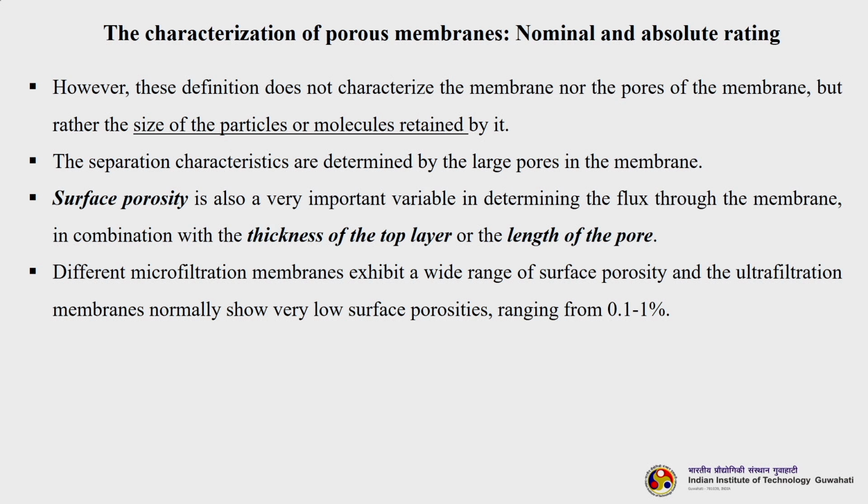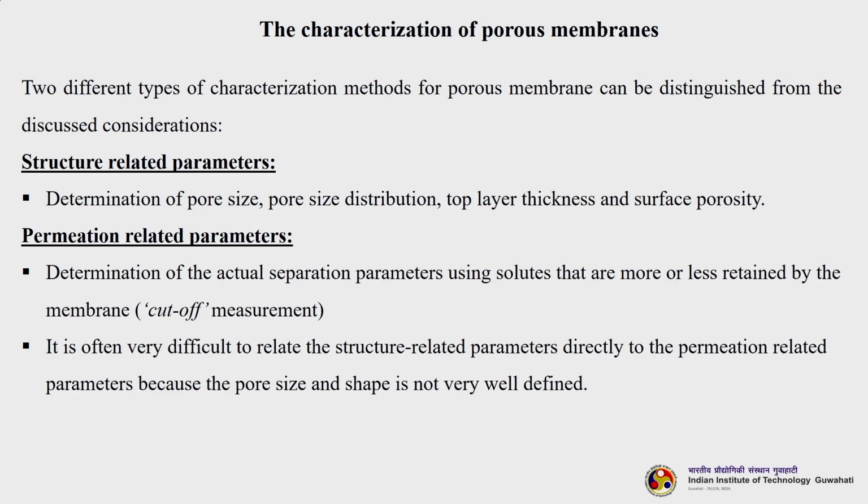Surface porosity means the number of pores actually present on the surface of a membrane, or per membrane area. Different microfiltration membranes exhibit a wide range of surface porosity, and ultrafiltration membranes normally show very low surface porosities, almost 0.1 to 1%.